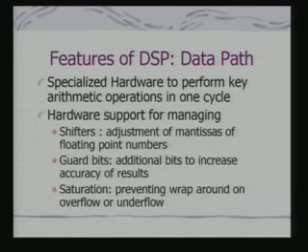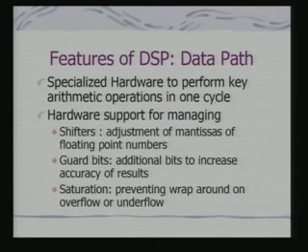It can be used very easily for adjustment of mantissas, because I have to make the exponent the same by adjusting the mantissas for doing any kind of floating point operation. Then many of these processors in their accumulators have got what are called guard bits, that means additional bits to increase the accuracy of the results,